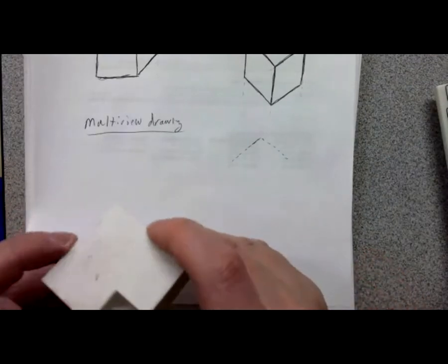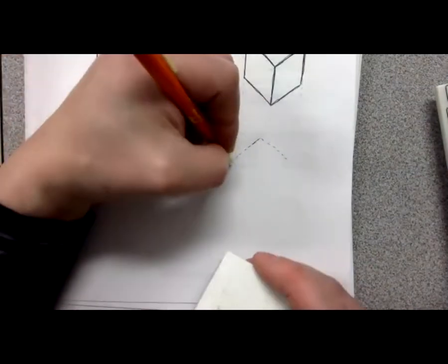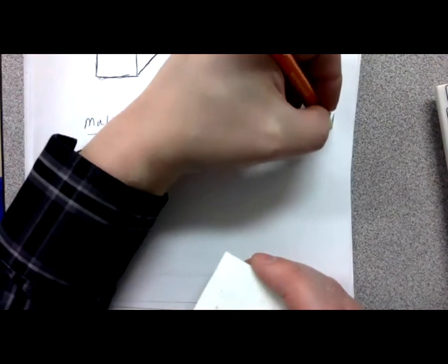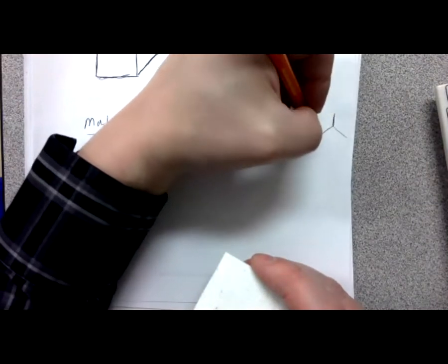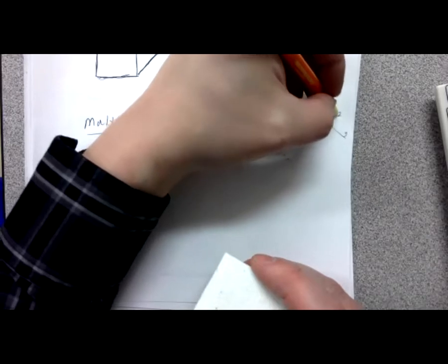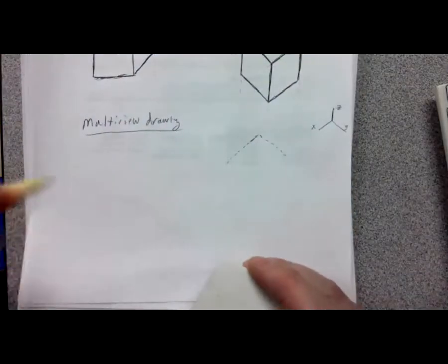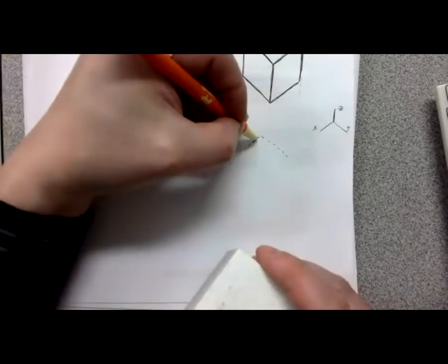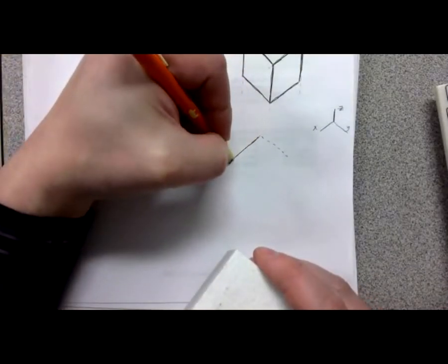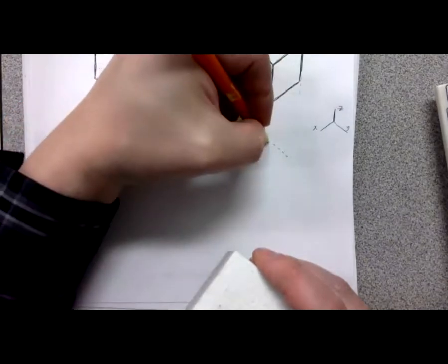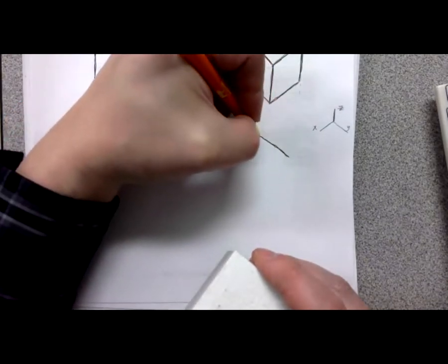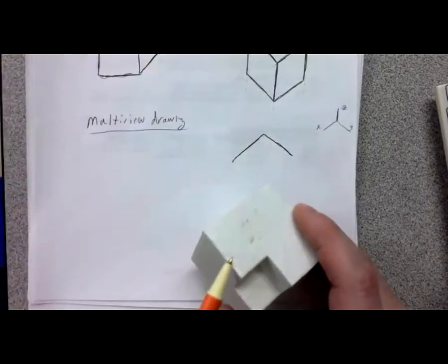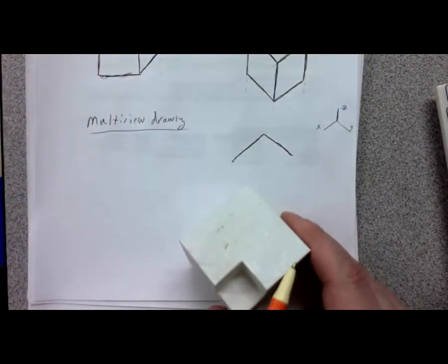So I'm drawing these lines here first. And again, as we said earlier, it's a good idea to draw your reference angles over here. This is X, Y, and Z. So I'm going to draw these lines on it, dot them in roughly, and then go back and make them good, solid, visible, thick lines, because they're visible in this view. I'm going to draw this line here and this line here.